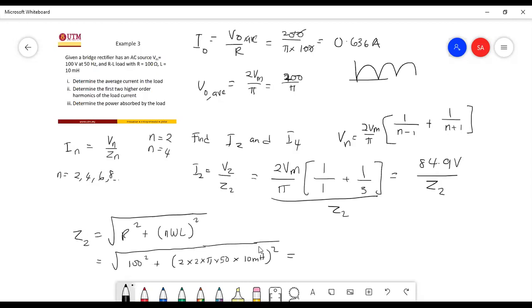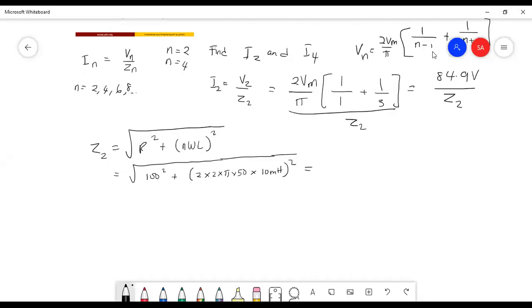So this one is actually just an impedance value. I think you can just use this one: Z2 is equal to R plus j 2 omega L. So what is the value? This one is 100 plus j, 2 multiplied with 6.28. Okay, and then convert into polar form.